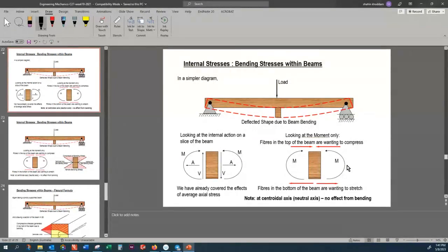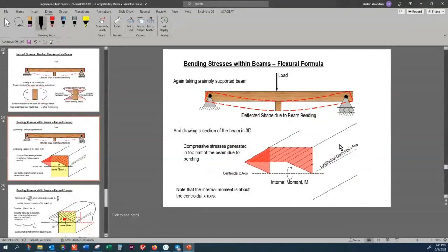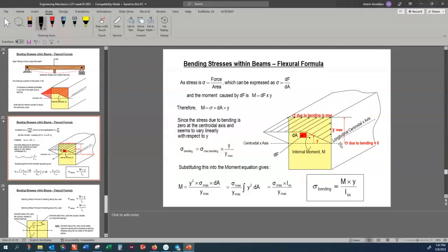So how can we verify the flexural formula? There are two approaches. We can make a strip. At point x, I can slice a section, where the thickness of my slice is delta x. I draw the free body diagram on this side, and by writing the balance of the free body diagram, which is a differential equation, I have to do the integration. That would give me the formula for flexural. But all you care about is the flexural formula here.